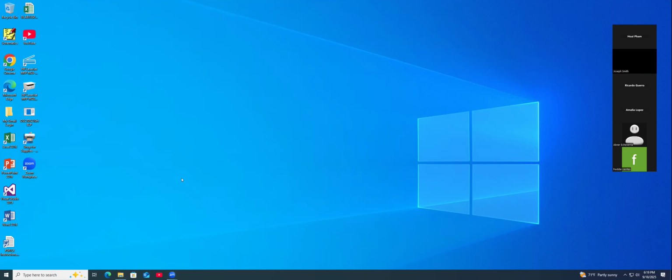So basically, the first time you want to do the lab using the generator and oscilloscope, first you connect the generator to channel 1 and channel 2, and you set windows 1, 2, 3, 4 to what you want, measure V peak to peak or frequency, and let it display on the oscilloscope.